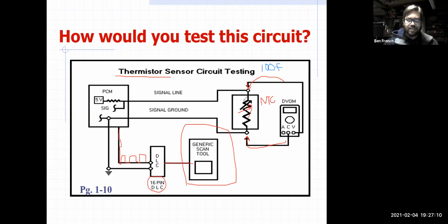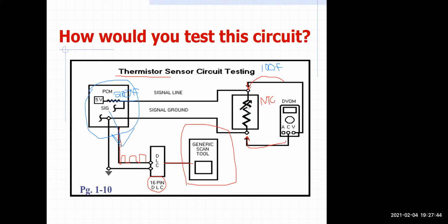But this sensor is messed up, and so the voltage drop across the sensor is very low. And this thing goes, oh, okay, well, you're really at, it interprets that as you're at 200 degrees. Okay. That's what it's going to then send to the computer. It's going to basically send the computer what it thinks is going on, not necessarily what is going on. Okay.